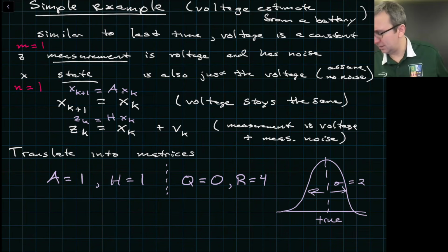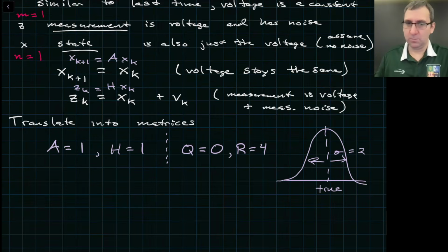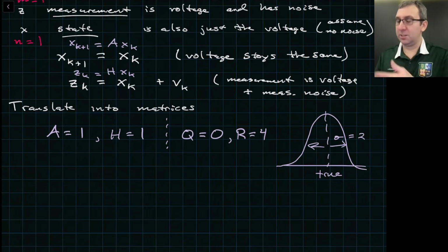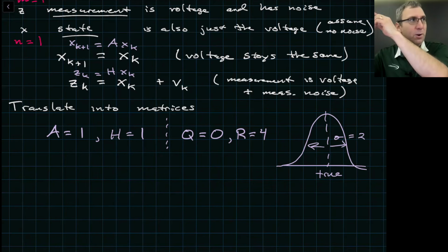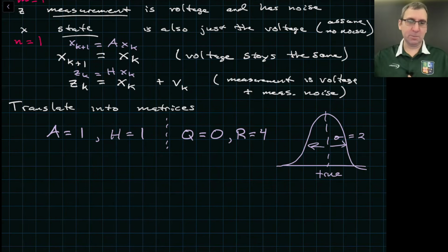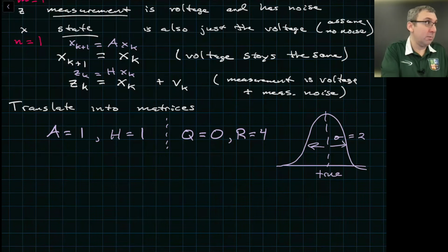What are the units here? Volts. Now, another thing that was the beginning of the diagram for the Kalman filter was you need to give it an initial guess. I think usually the initial guess doesn't matter. It just sort of speeds up your thing. Usually you get this from experience. So from experience, we've seen that the voltage is around 14.